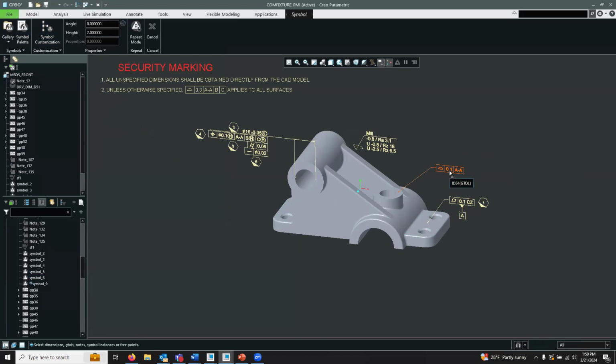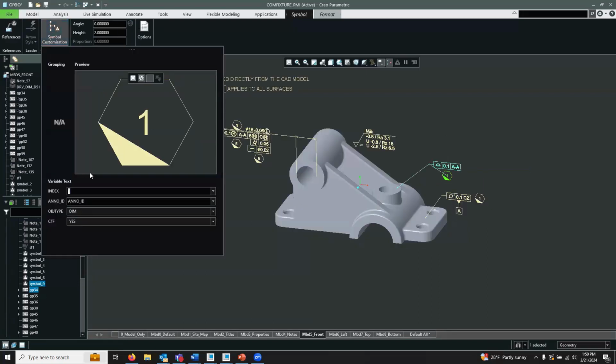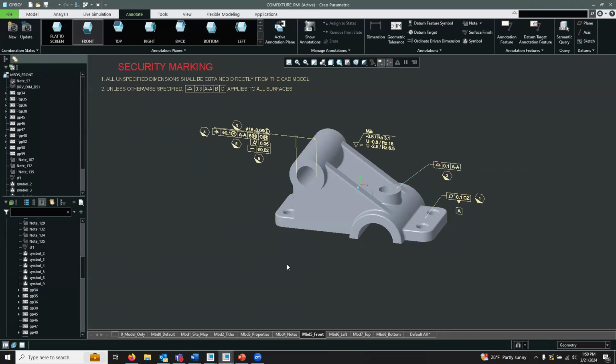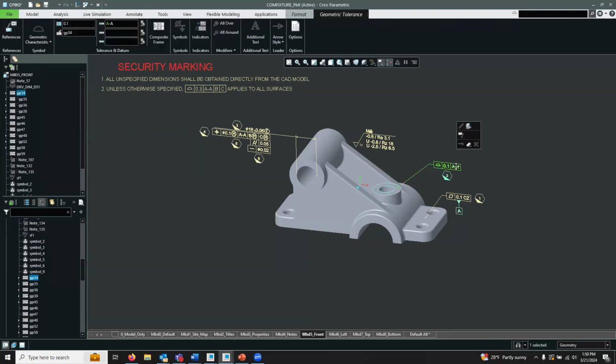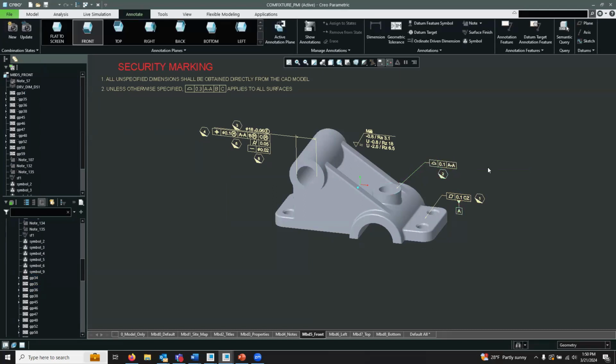So how this works, I'm just going to click once to associate this symbol. And we'll see it's now associated with this annotation. And then I'm going to be able to click again or middle mouse button to actually place. So let's see, I'll go ahead and place this right here. I'm just going to change that to a 2. And we're all good. So now when I go to move this, they're going to move together. They're going to remain associated. This is something that should have been in this mode forever, but was recently added, and it's a big usability improvement for complex tolerances.